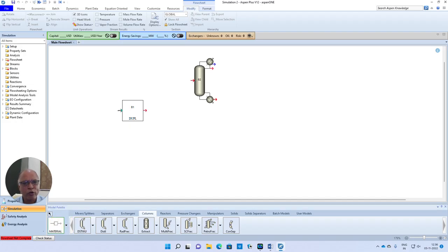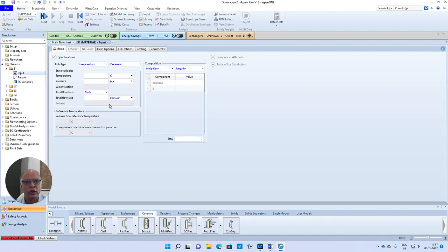You will have the advantage of simulating using shortcut distillation, though it may not be very accurate because you are using certain formulae, Winn-Underwood-Gilliland correlations to calculate or design the column, which may not be really very accurate, especially when you are dealing with non-ideal systems. So having defined this, let us go and try to complete our problem definition.